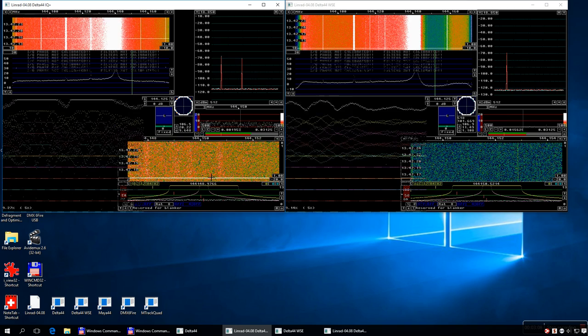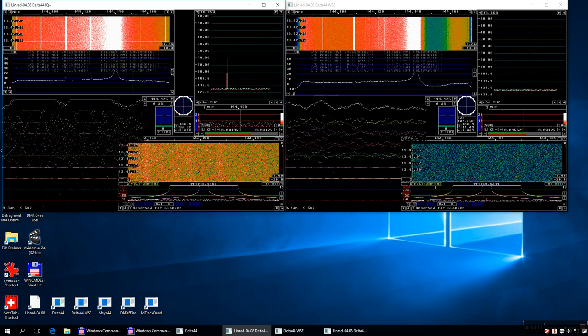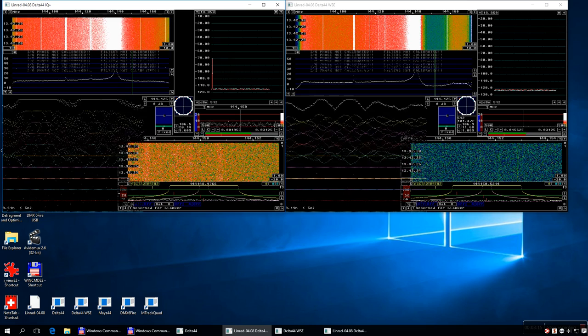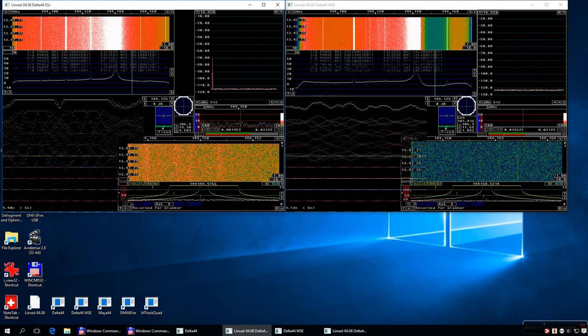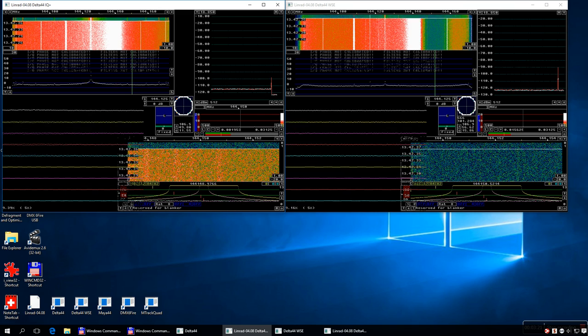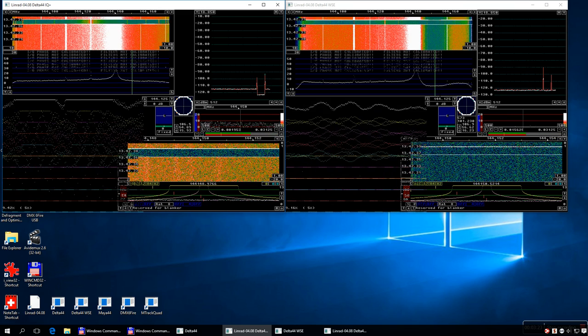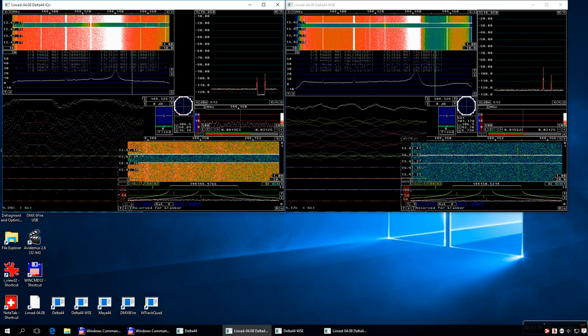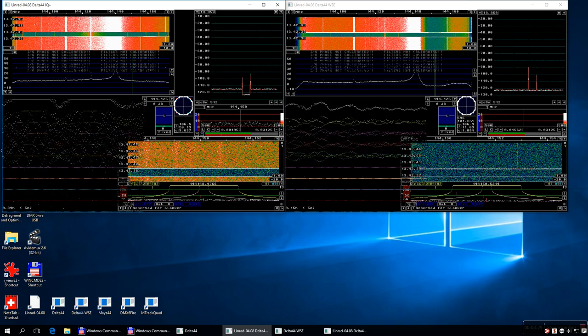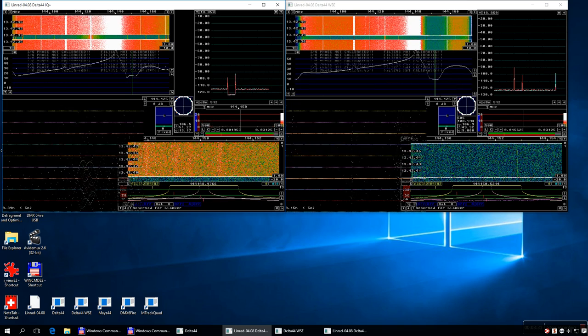There is a range where the noise floor is unaffected by the strong signal. You can see if I switch it off and on again. That's because I have a notch filter. You can see the presence of the notch filter on the transient when switching.